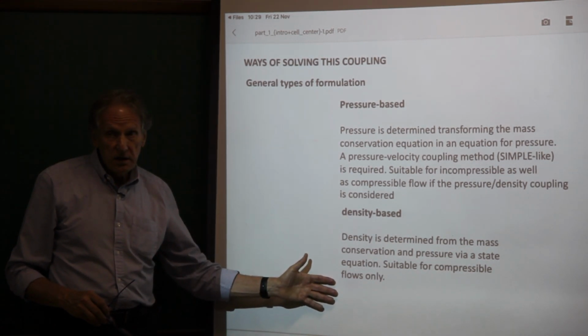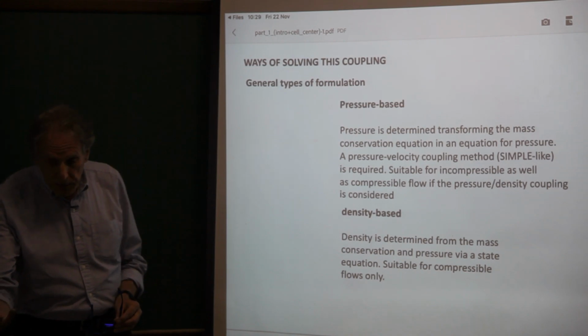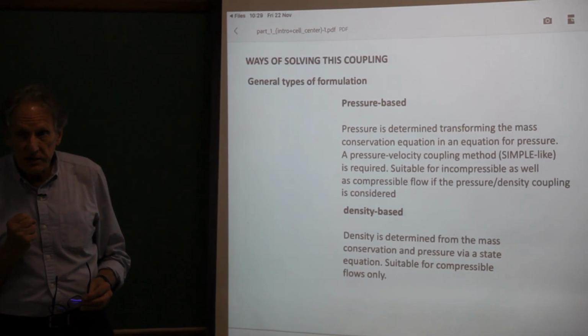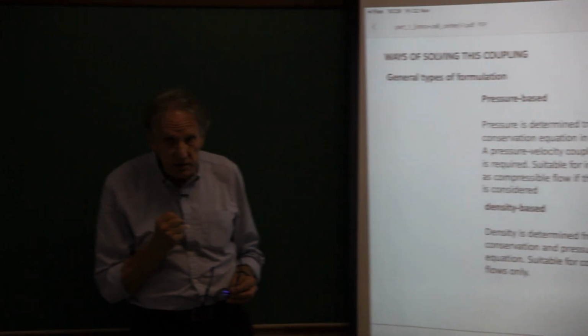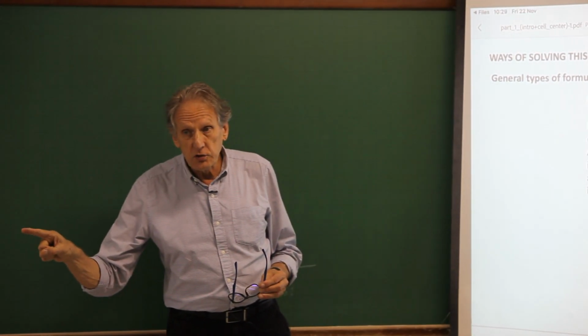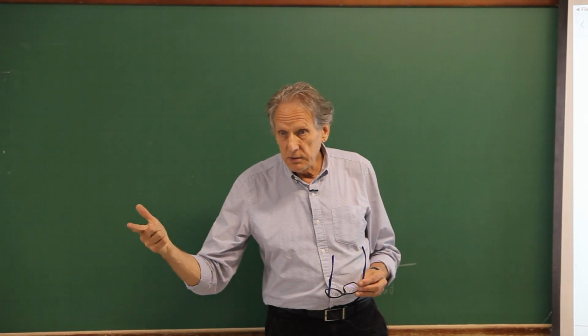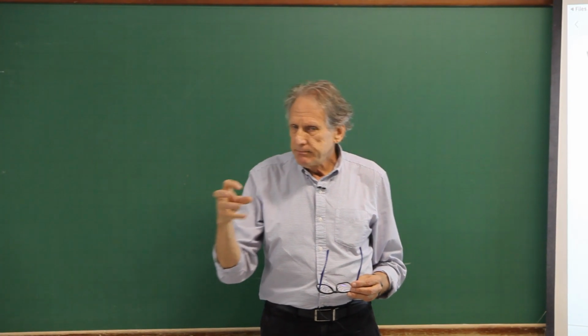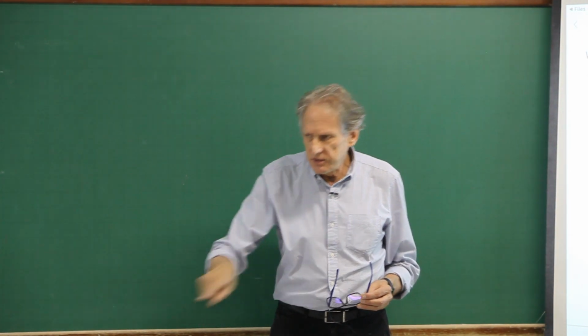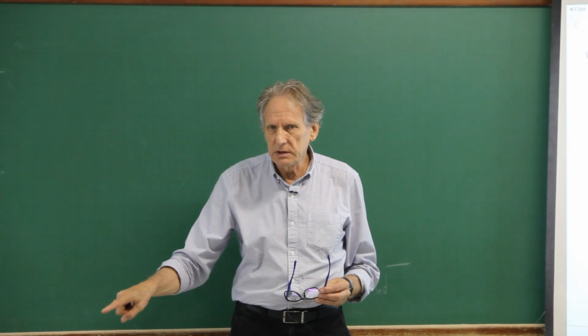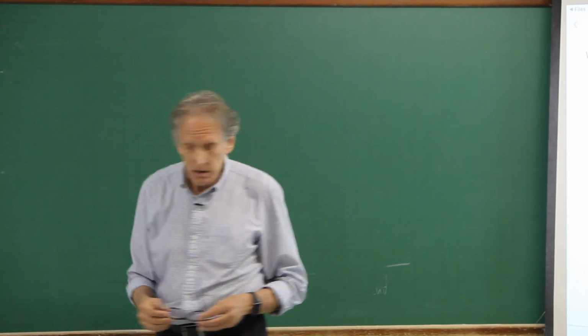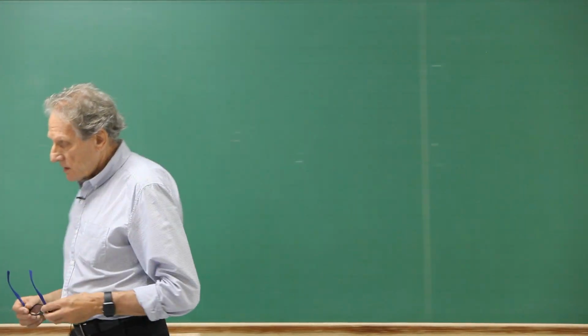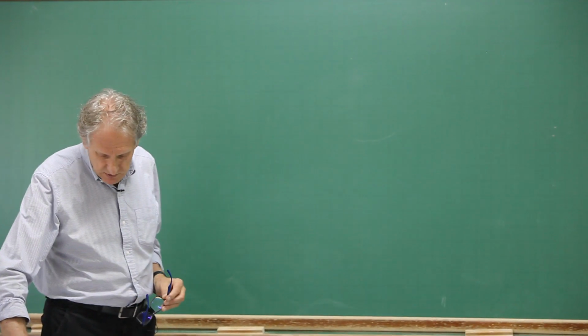Density-based is the one which recovers the density from the mass conservation equation, and then pressure is obtained with the state equation. But if you have a state equation, it's a compressible flow, so that's suitable for that. So pressure-based and density-based.